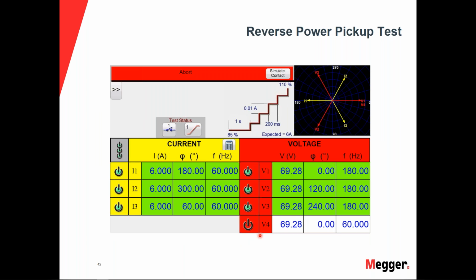Here's an idea how to test it. What we're doing is just a simple 3-phase test. We come in with nominal voltage in the forward direction, and then we can change the current values, so 180 out, and get to the watt setting. We would have to take that watt setting and calculate it using the voltage that we're actually going to use for our test. That will give us the current value that we're going to apply for the test itself. And then we're just going to reverse that current as far as the phase angles, bring everybody 180 out, as you can see in the diagram here.